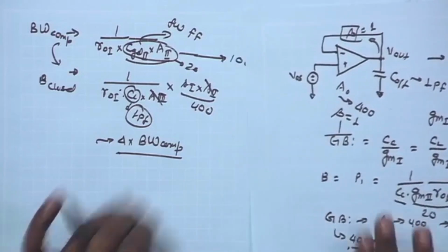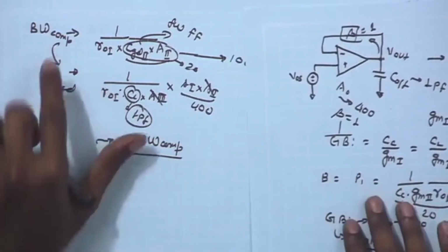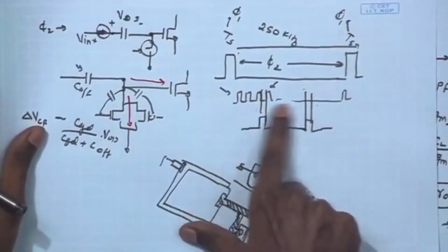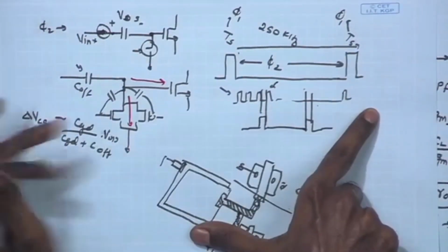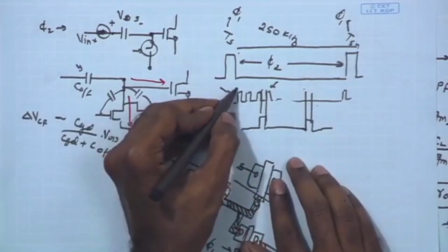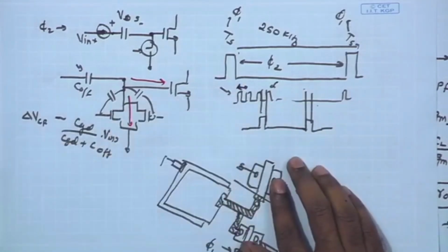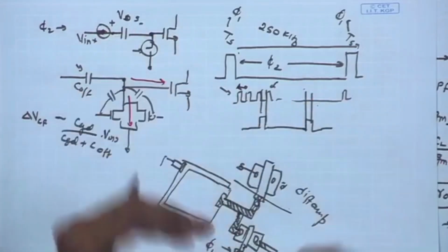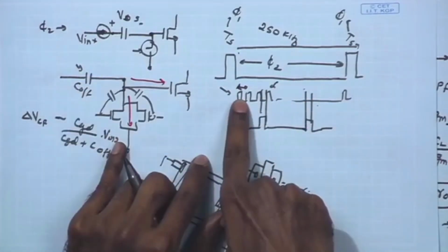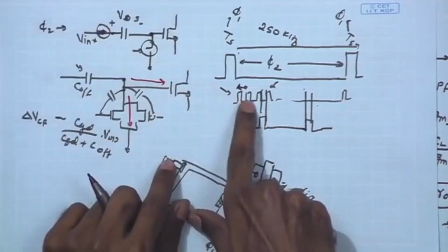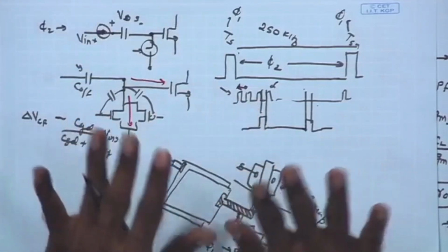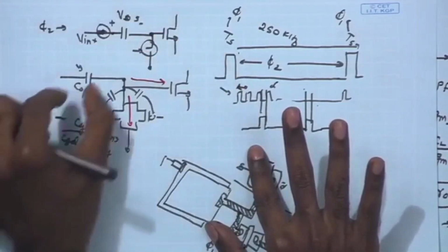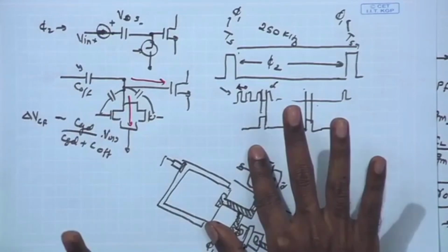So, if that happens, what will be the constraint? As of now, it seems like we can go to our original waveform and our comparator can operate faster than this clock, that is how we have designed. So, within one clock period it can settle nicely. The closed loop bandwidth for the unity gain feedback is also even further larger. Therefore, within one clock duration it can do the offset calibration, it can store the offset value across the C offset. That is what we are concluding.